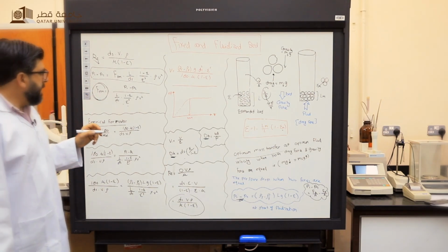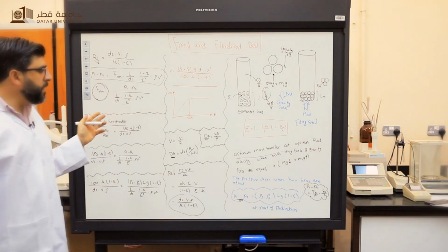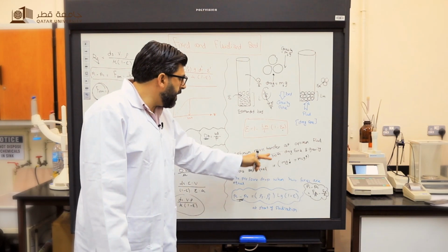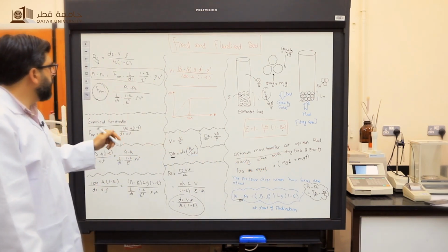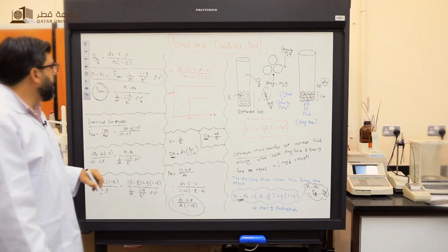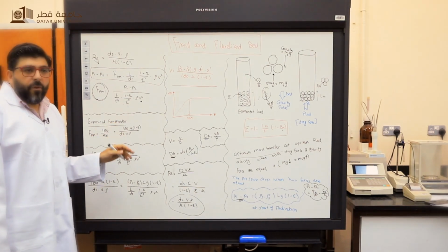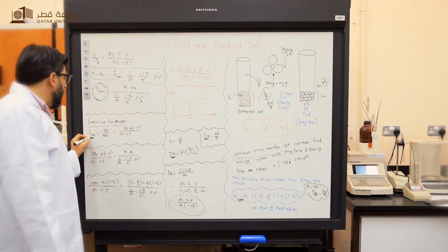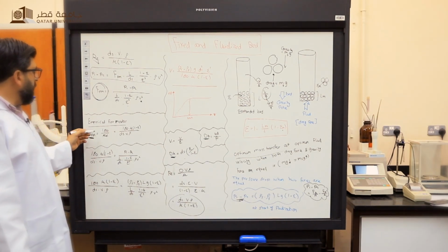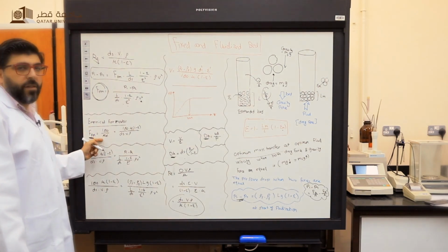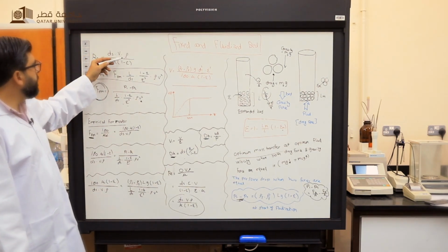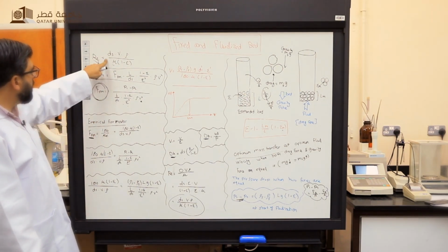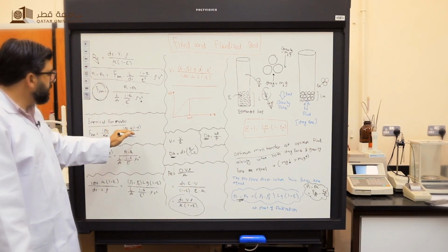Okay. Why am I doing this? I'm doing this because I want to find the optimum mass transfer at the minimum fluidization velocity. So I want to determine V. From the empirical formula, they found that the friction factor for the porous medium equals 180 over the Reynolds number. We said the Reynolds number is ds V rho over mu, times 1 minus epsilon. If we replace the Reynolds number by this value, we can get this new formula.